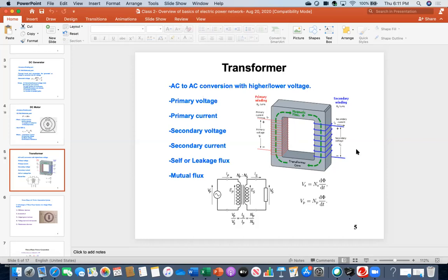Dr. Ali, can we use a transformer as a DC filter or something like that, so that we can remove the DC? A transformer sometimes can be used as a filter. What is the equivalent circuit of a transformer? Look at this one. What can you see? Primary and secondary coils. Just the coil. And what is a coil? A coil is nothing but an inductor. So what is the function of an inductor? The property of an inductor is that across an inductor, current can't change instantaneously.